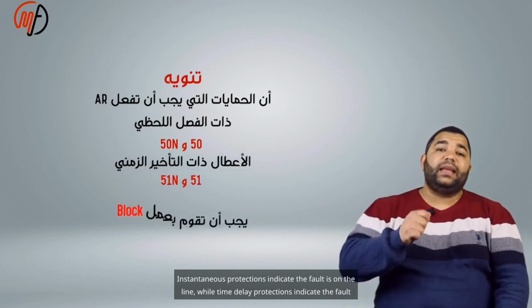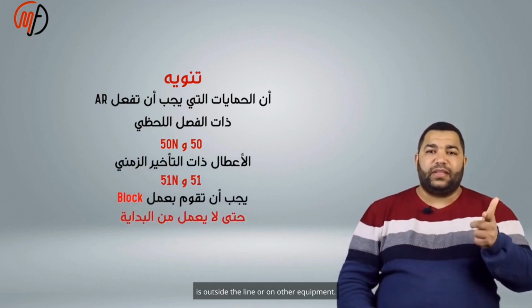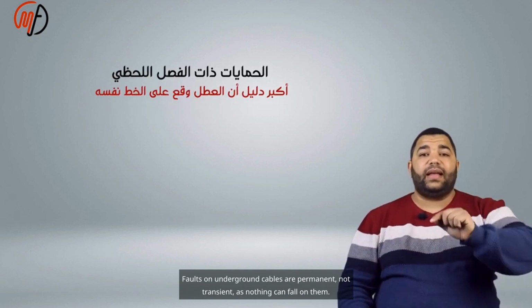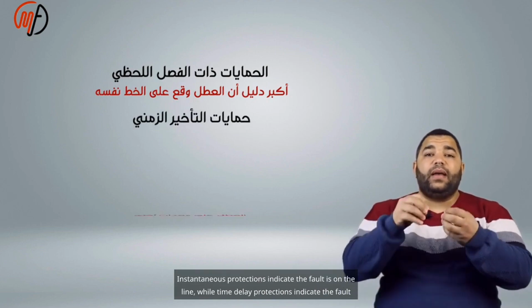Instantaneous protections indicate the fault is on the line, while time delay protections indicate the fault is outside the line or on other equipment. Faults on underground cables are permanent, not transient, as nothing can fall on them. Block the autocloser from the start.